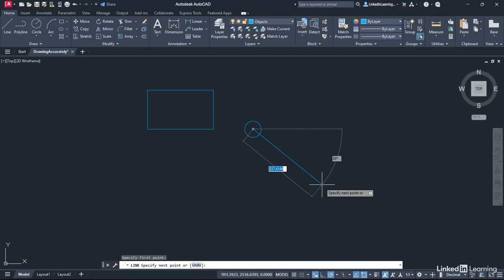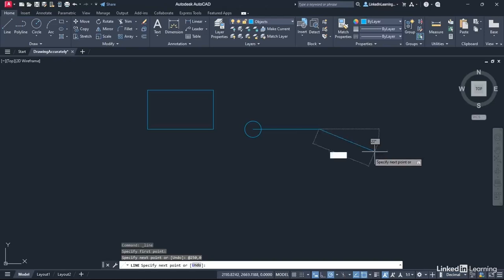We're going to type the @ symbol. So I'm going to type @ like so. Can you see that appears on the dynamic input entry like so? And we need that to be 250 long along the x-axis, but 0 going vertically on the y-axis. So we're going to type in 250, comma 0. Now that line will go to the right because it's positive, and it will be horizontal because the y value is 0. Press enter, even though the line looks a bit weird, and you'll see there's your 250 long line. And now we're ready to come off of that segment there.